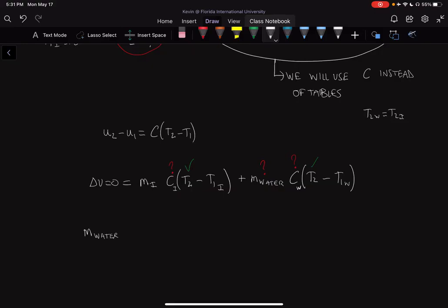Well, the mass of the water is equal to V over specific volume. So what we can do is go to table A4 and assume that we have a saturated liquid, because it's pretty much incompressible. We can use our compressed liquid rule, where we say we have a compressed liquid. We know that. Therefore,